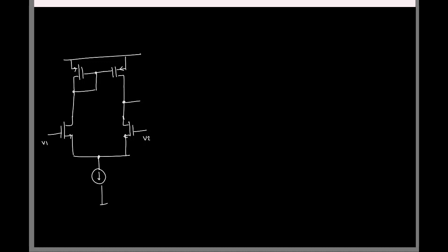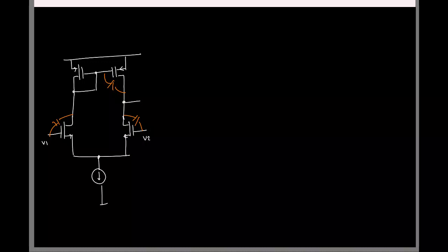So again we can start to mark the capacitances one by one. Now obviously from each of the nodes to ground you will have a capacitance, right? And that will be due to whatever, source to bulk, drain to bulk, whatever. And we will also have the CGD capacitances everywhere. But of course now you see you add capacitances at each of the nodes, things actually become quite complicated. So what we'll do is we'll make some assumptions. So let me erase this. Okay, we'll make some approximation.